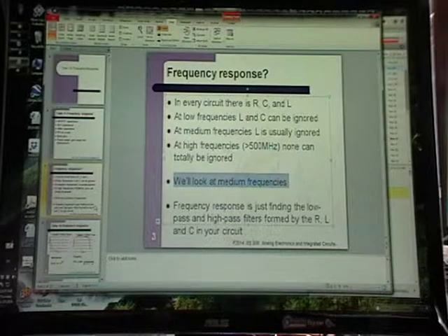We are going to add capacitors to make our intentional poles. If you're using an AC coupling cap, you'll also see a zero in there. But anyway, we are going to add capacitors to create poles so we can observe them. Just because our equipment can't see the frequencies of the poles that naturally exist, we are going to artificially create poles by adding capacitors to our amplifier. I think I've said that enough times. Okay.